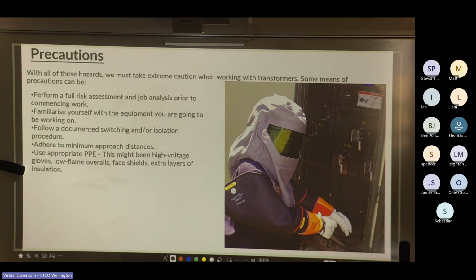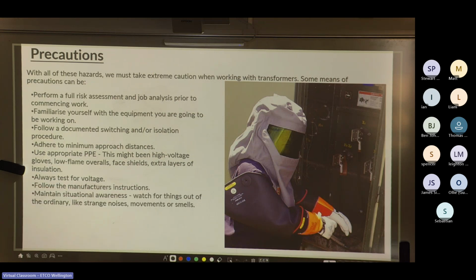Follow appropriate PPE. This might be high voltage gloves, flame-retardant overalls, face shield, extra layers of insulation, or the bomb suit as pictured there, as the guys like to call it. Always test for voltage. Follow the manufacturer's instructions. Maintain situational awareness. Watch for things out of the ordinary, like strange noises, movements, or smells. If it makes a weird buzzing noise, stop, drop, and roll. Keep track of all tools and equipment used in the transformer. Never work alone. Never become complacent.